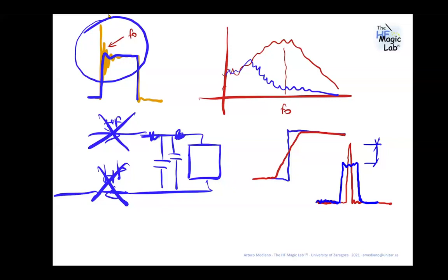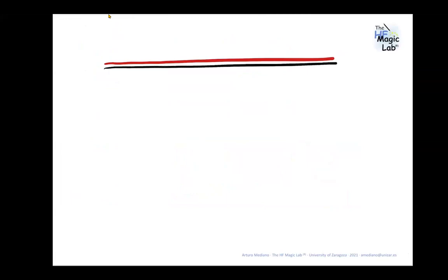Can we twist the cables to reduce capacitance? I'm not sure what capacitance he's explaining, but consider that if you have a red and a black wire, and one is very close to the other, and you compare the capacitance between the cables when you make a twisted pair, the effect of the twisted pair is that capacitance between the wires increases, it is not reduced.